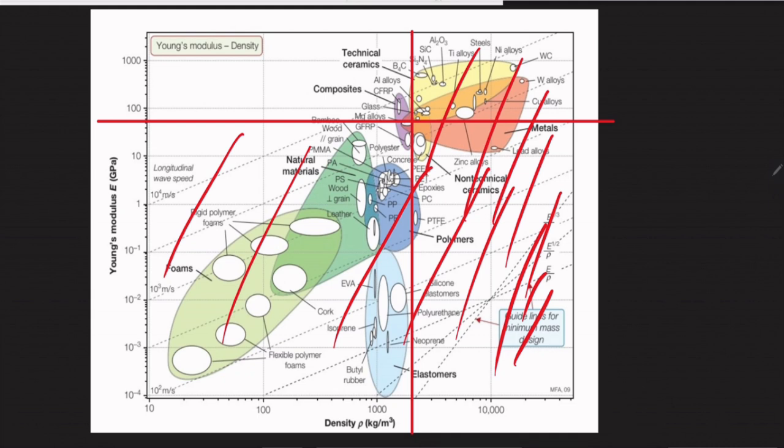So our best materials with both properties are what? CFRP. If you look at here, we have what? CFRP, carbon fiber reinforced polymer. So CFRP, and the next one is, if you look at here, which other material passed our selection? So technically, we have just carbon fiber reinforced plastics as our best material that passed the selection. So this is the material that we are selecting for this particular application.